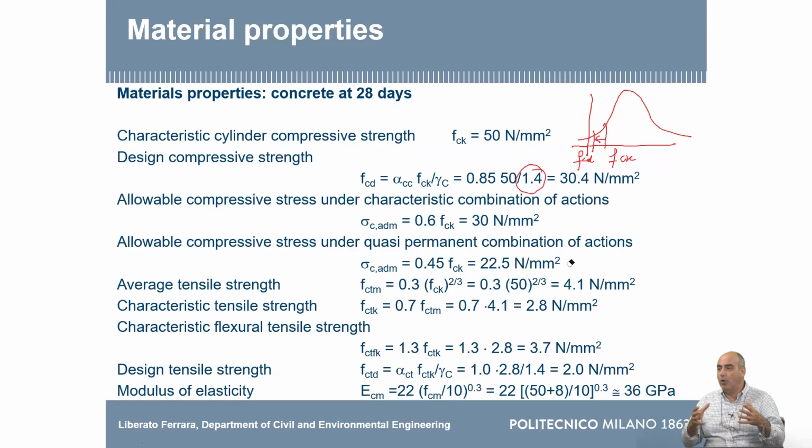So the live load for this room has a fixed part, which are the floors and the furniture, but also a variable part, which goes back and forth. So not all of the live load produces creep. Only what we call the quasi-permanent part of the load.